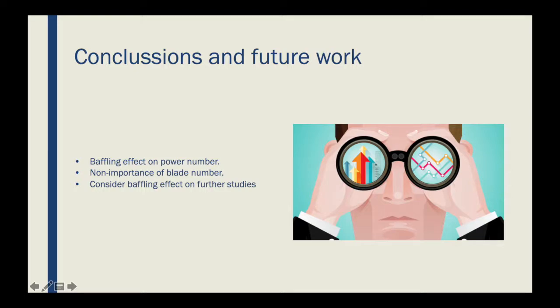As a conclusion, the impeller blade number is not a significant factor that affects the power number, so it's important to take into account the baffling for future studies, because the power number for most impellers remains constant in the baffled configuration, while it decreases with an unbaffled configuration.